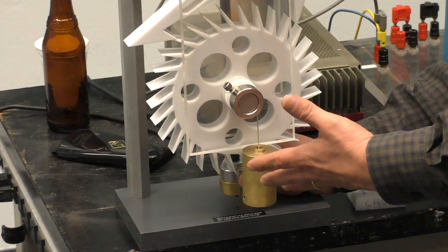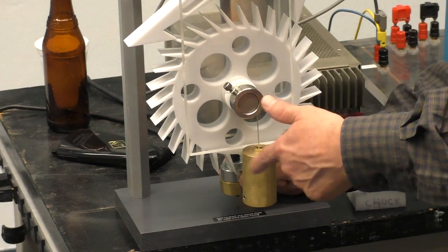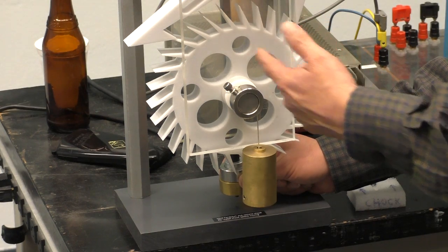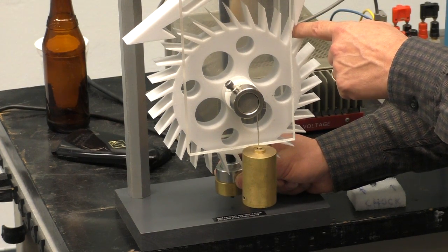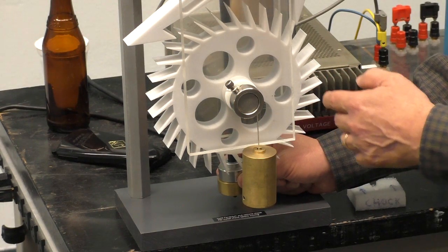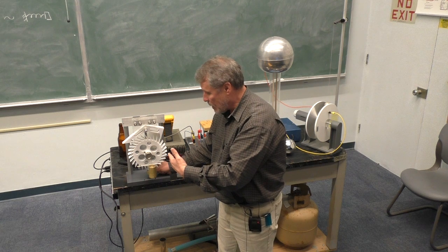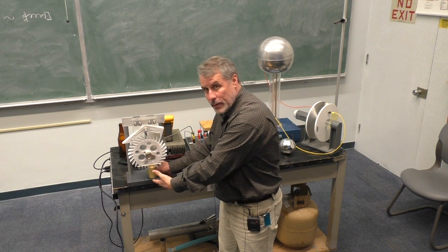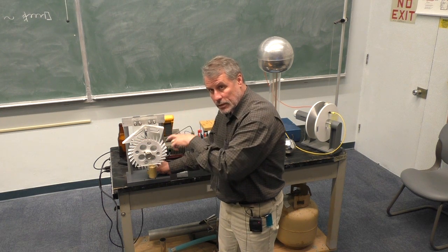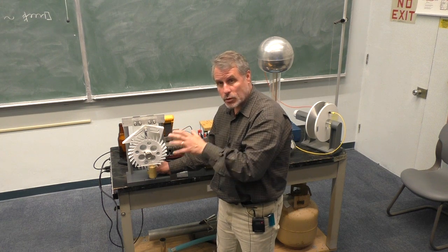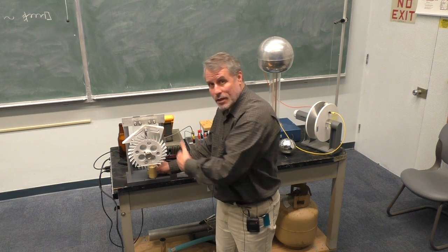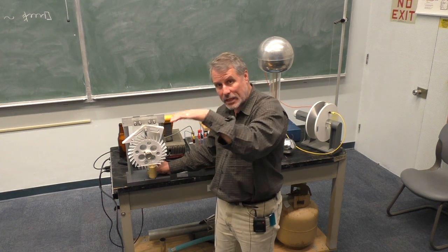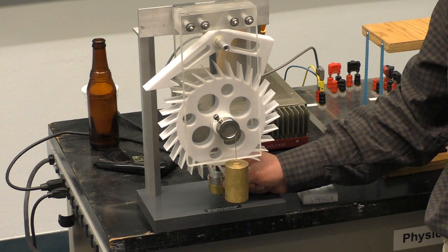Gravity is acting on this weight to bring it down. That spins this wheel, but this wheel is stopped at two particular places, at those indentations. And so the escapement mechanism results in an oscillation driven by a DC force, zero frequency, but there is a modulation of the energy between the DC force and the oscillator, and that modulation is taking place with the teeth of this wheel. Notice that there is a particular orientation that allows that flow of energy to be modulated.